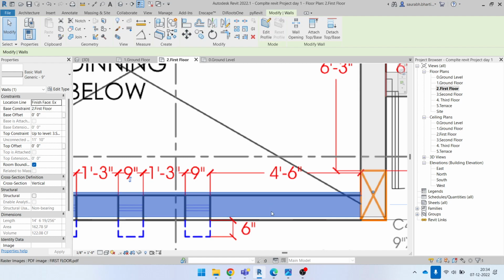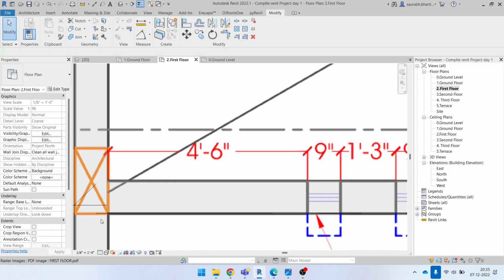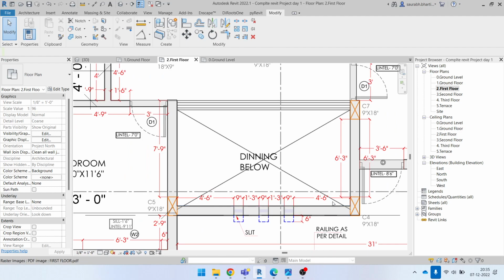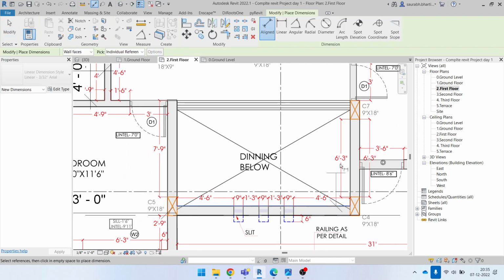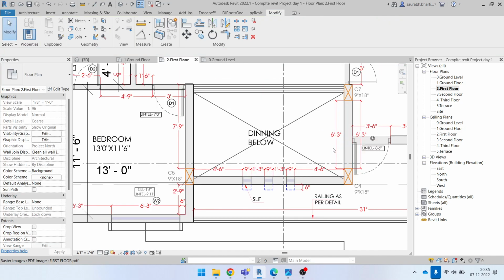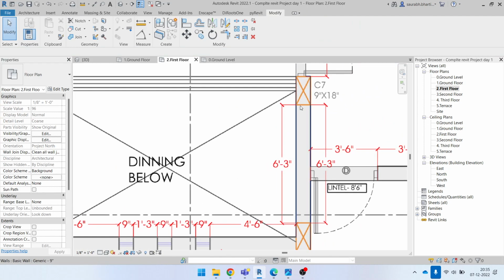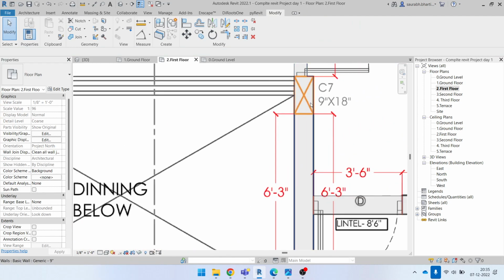So as you can see there, we are getting 4 arrows here. I will just left click here, and now you can see you can move it. And if you try to move it over this place, it will automatically get attached to the place where we have snaps enabled. Okay, and if I take the dimension from this part, we don't have anything here. So if we just put a line or anything here, because we have a column here. Okay, so we can put the column, but we are not going to put a column right now.